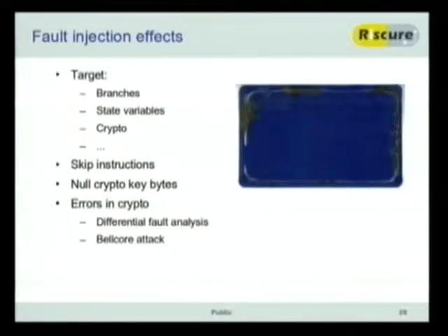There's actually one attack that, if you have an RSA Chinese remainder theorem implementation, you can glitch it once and do one normal execution, and just from the difference of those two you can recover the entire key, which is pretty strong, you could say. Now if you really want to kill your target, that's not too visible. There's actually somebody who tried to do fault injection using a microwave oven. That was more of a permanent glitch.